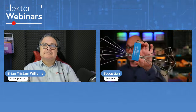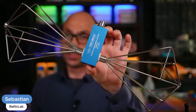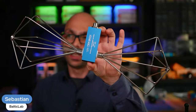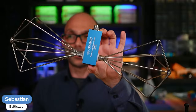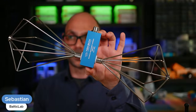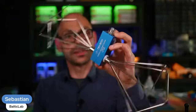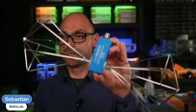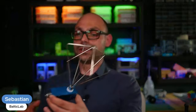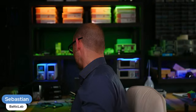This one here, for instance, I've shown this before multiple times. This is a biconical antenna usually used for EMC measurements. What's special about it is that there are known antenna factors for every frequency in its range, which is 30 megahertz to, like, is it 3 gigahertz or 300 megahertz? So you can really make accurate measurements with that if you apply the antenna factors as correction factors. And if you don't have access to the antenna port, this is what you'll have to do.